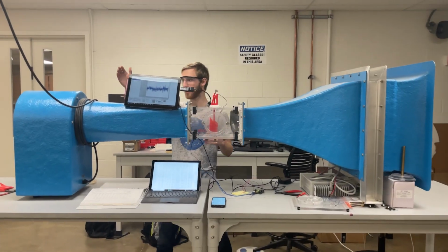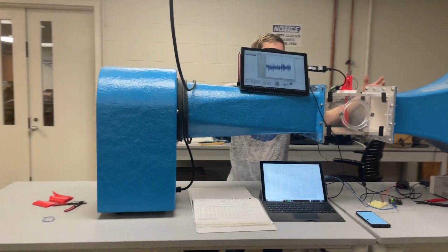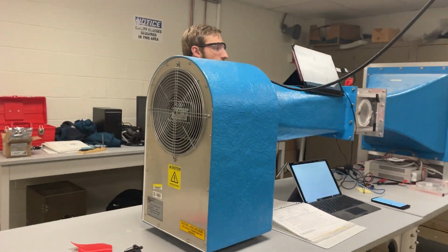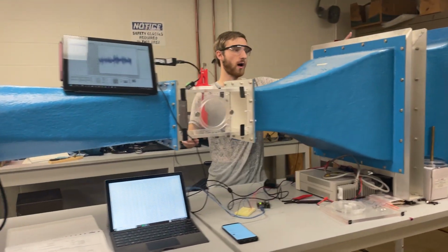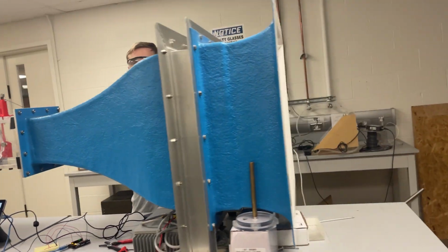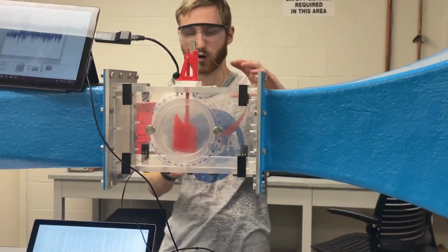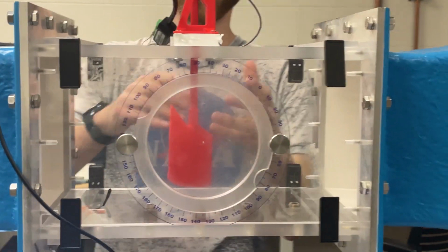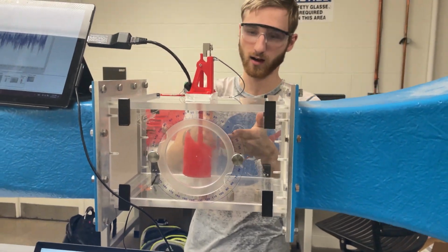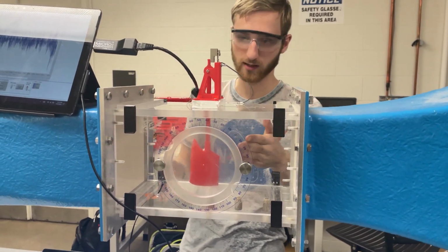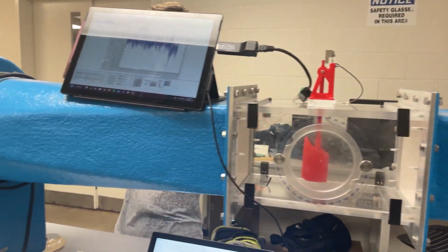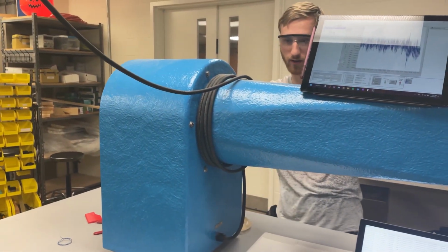So as you can see, the fan on this side pulls in air through our controlled wind tunnel environment. It comes straight through our straightening section on this side, which basically has a bunch of little passages to have laminar flow come through and then shrink down to our particular test section over here, where we have our actual fin, our turbine fin sitting here ready to be measured. And then it comes through here and then exhausts through the back over here.